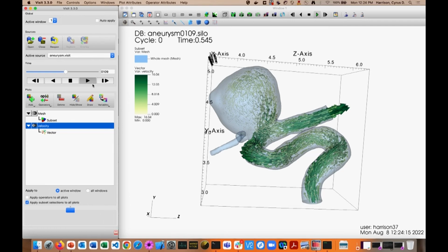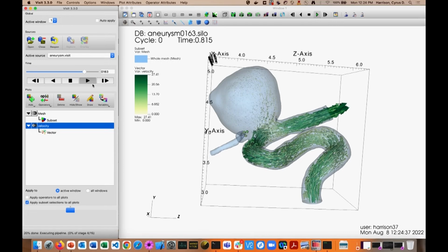So streamlines will tell you, if this was a steady state simulation, if this wasn't moving, given the vector field you have now, if you had vectored it to infinity, or to some start point, where it would go. But path lines can actually read every time step and say, okay, the vector field changes every time step. We're going to move particles a little bit, then a little bit more, and a little bit more, and we're going to take that all into consideration.